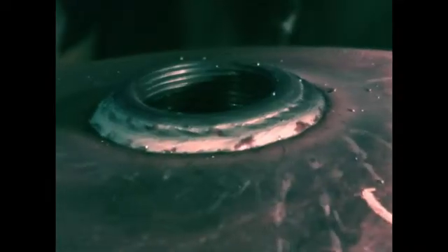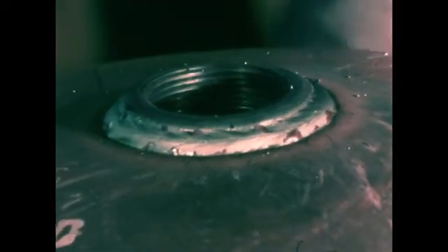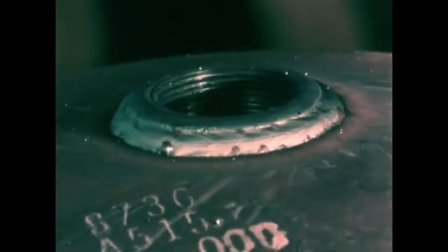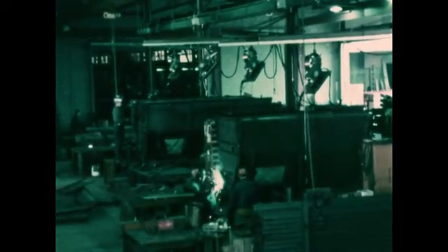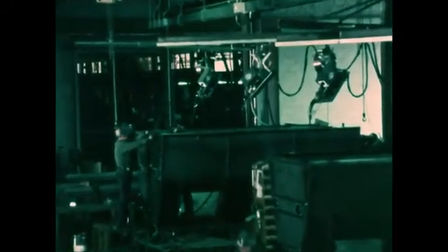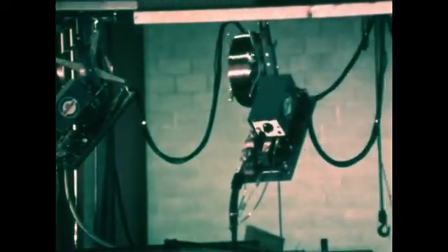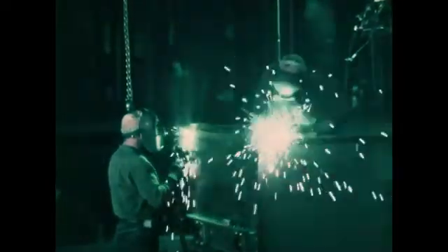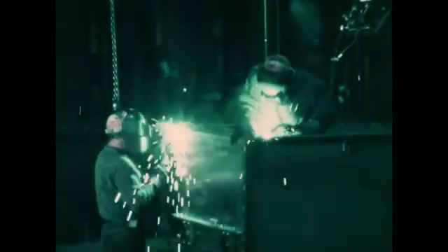Where the work can be fixtured, the lightweight welding gun permits operators to easily complete uniform and X-ray quality welds on a continuing basis throughout a work shift. Clean, smoothly deposited, and efficient welds of this type are typical. Modern shops encountering all types of welding needs will often bring their shielding gas supply to the welding gun via a piped or manifold system. Wire feeders also may be suspended overhead and out of the way of worker or materials movement requirements. Several operators may work on one job and never get in each other's way.